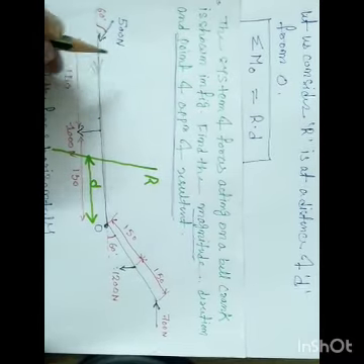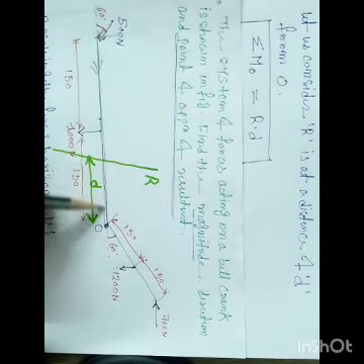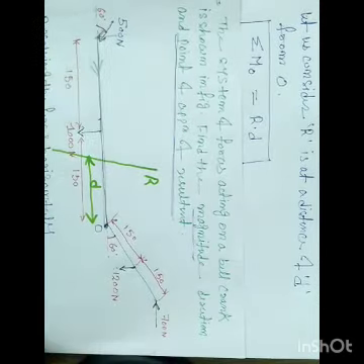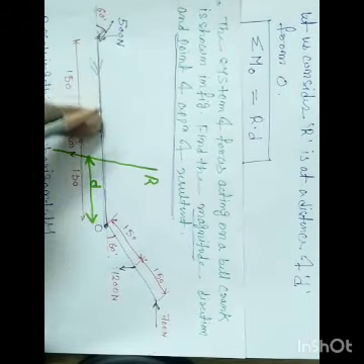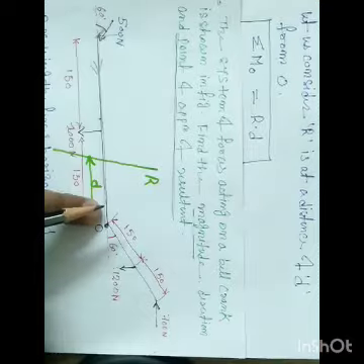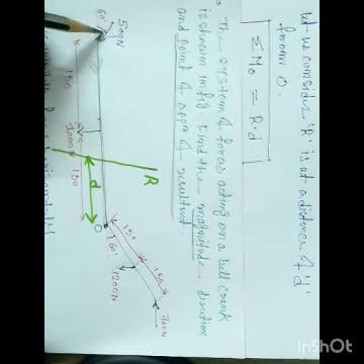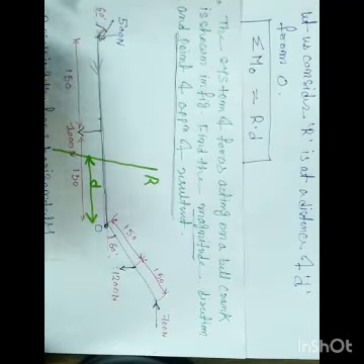This force is inclined, so we'll get its components, the horizontal component like this and the vertical component like this. If I take the horizontal component, we don't have any perpendicular distance. The condition for moment is force into perpendicular distance. If you take the force as horizontal, the distance should be perpendicular. But if I take this vertical component, we have a distance which is perpendicular to it.